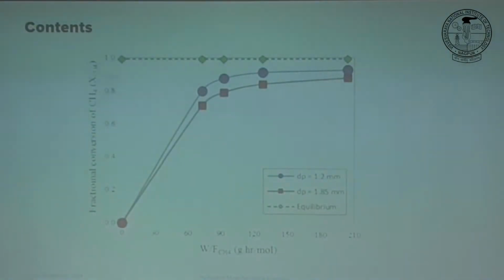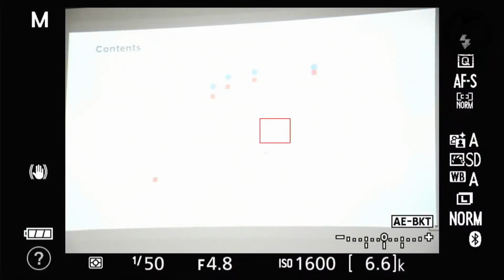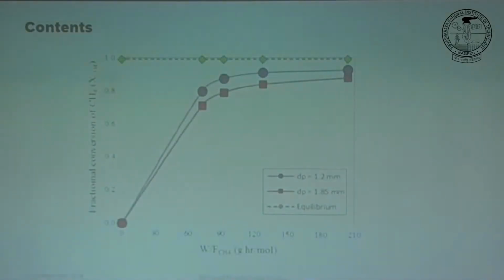And the three plots are for different pore sizes, depending on different metal loading on the catalyst, right? So with this graph we know already the amount of catalyst for a certain flow rate, this ratio I need, and even if I put in more catalyst, it's not going to help us in conversion, right?